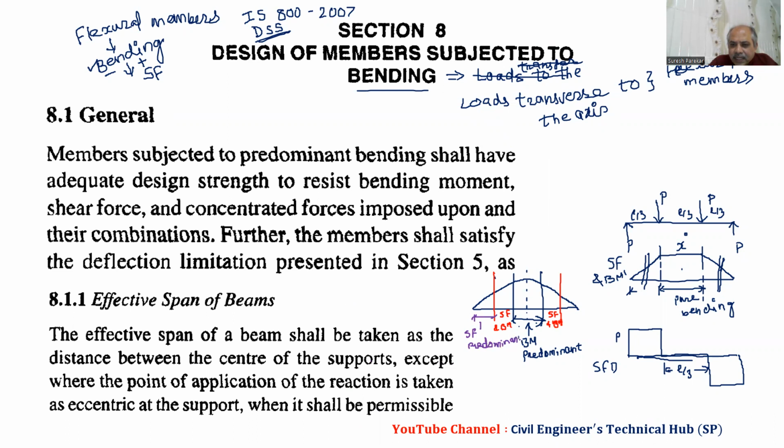So we have these regions, and we are interested in this. This is bending moment predominant, and shear force and bending moment considerable means both are considerable in the design. Only shear force predominant we are not going to study in this flexural member, because then that member goes to shear, and design for shear is not in our syllabus.